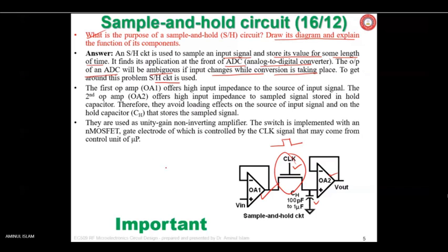Okay, when the converter, the ADC, analog to digital converter, is converting, during that time the input should not change. If it is changing, then actually you will not be able to say what the value and output value is, and whether it is correct or not.